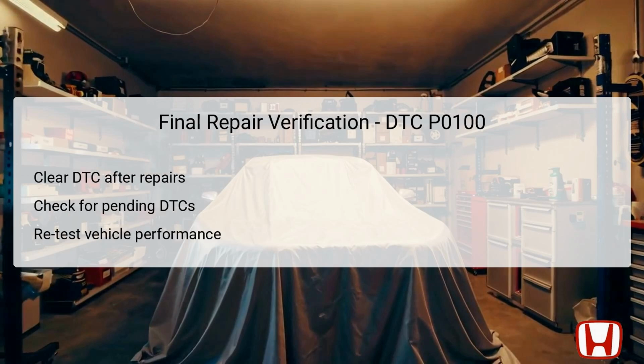After completing repairs related to DTC P0100, it's essential to verify that the issue has been resolved. Begin this verification process by clearing all diagnostic trouble codes using the HDS. Once you clear the codes, you must monitor the system for any pending or confirmed DTCs to ensure that the repairs were successful.